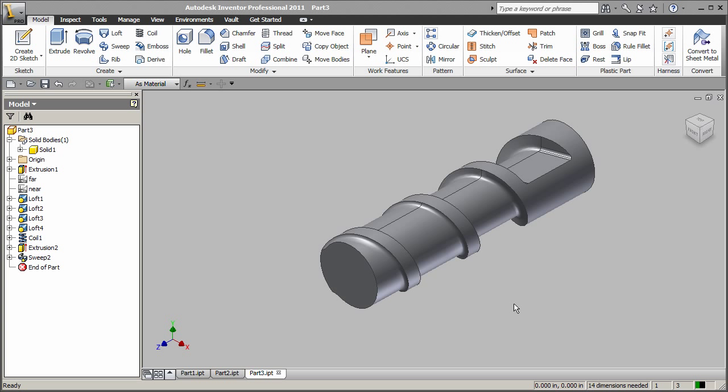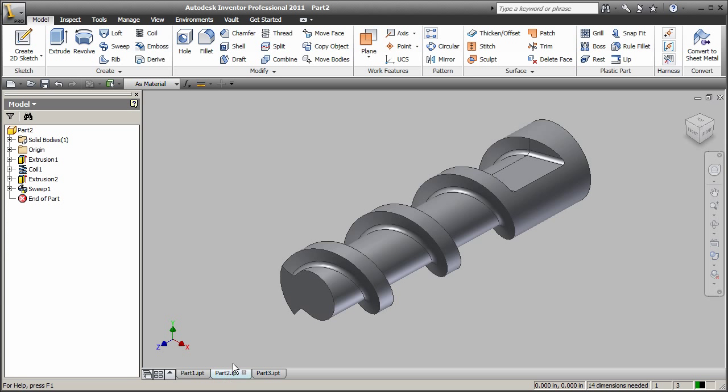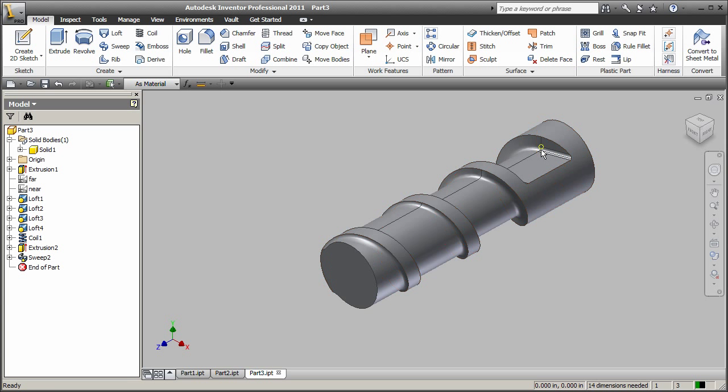Today we're going to create a feed screw with a transitional flight depth. Now it's easy to create a feed screw with an even flight depth. You simply create a geometry, a cut geometry, and then use the cut coil tool. Okay? But we want a transitional depth. In this case, we're going from 1/4 inch to 50 thousandths. So let's go ahead and get started.